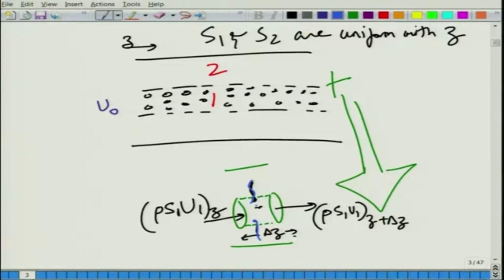There are different approaches of dealing with perforates. The one that we will be following, and what others have also followed throughout the literature, is that this surface is considered a porous surface with certain porosity. It is like a permeable surface allowing waves to go through with some sort of resistance or impedance, what we call. Wherever we have a perforate surface, we often define a quantity as the difference in the perturbation pressure across this element divided by the normalized velocity, that is rho naught C naught into u, which is assumed to be constant across the interface. This ratio is called the perforate impedance.